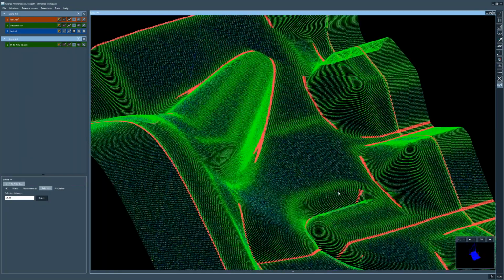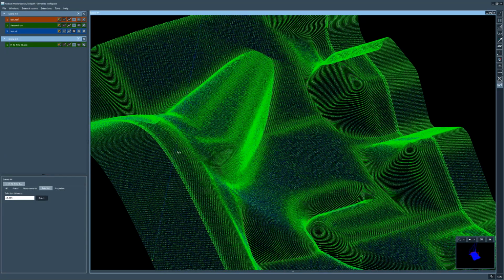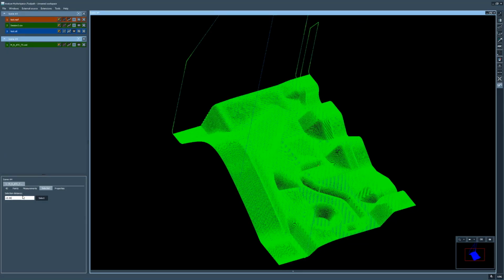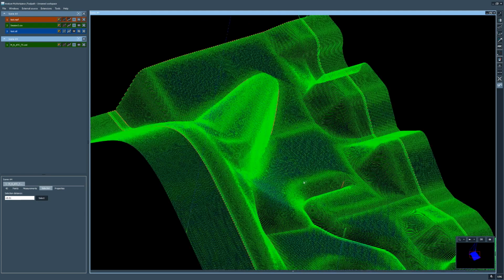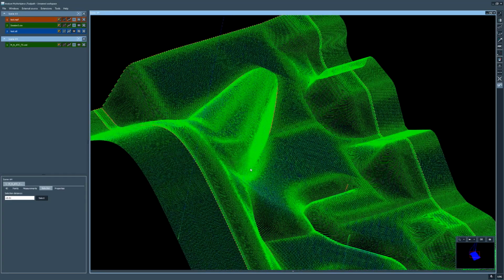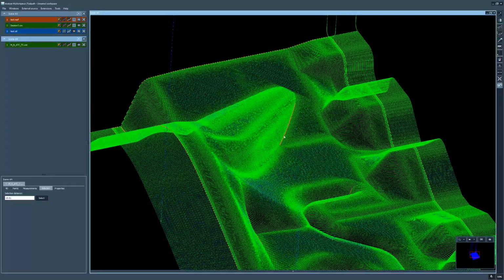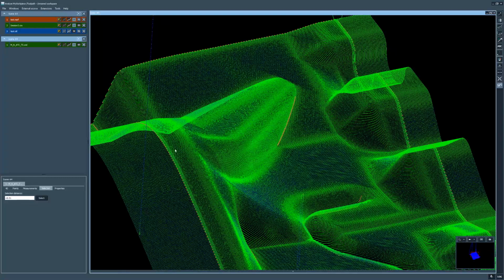Why is there such a tool? Well, these are the areas, let's go even a little bit smaller. Let's see whether there is something. Yeah, okay, Toolpath didn't find anything, maybe too small. These are the areas where sometimes the machine tool also slowed down. And using this tool, it will directly indicate where those areas could be.